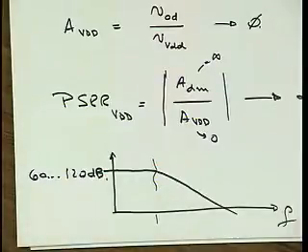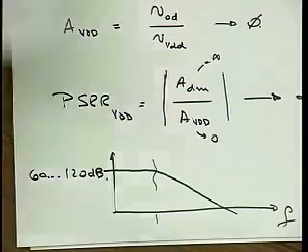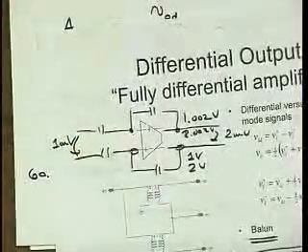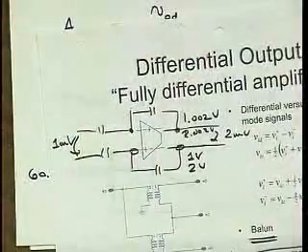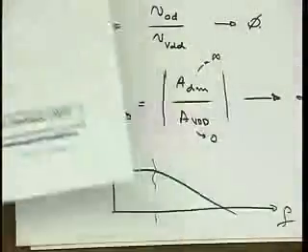But really, the power supply is hooked up through presumably a current source or whatnot, really to the output, both the positive and negative output of the amplifier, and consequently affecting both of them about the same if they are carefully laid out and really symmetrical. Consequently, to first order, the power supply rejection ratio of a fully differential amplifier indeed should be about infinite, very large.